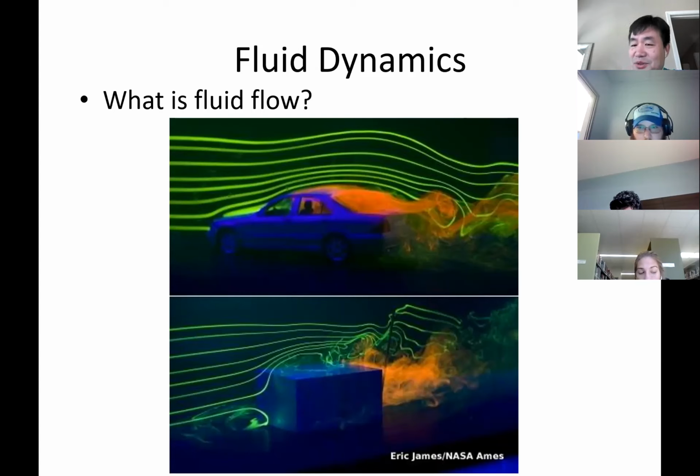Usually, if you can achieve that, this is a good race car. To stick on the ground is the lift. You have to have the opposite lift. You don't want the car to fly up. You want the lift going downward, negative lift, to make it stick on the ground, even at high speed. Then you want to reduce the drag.